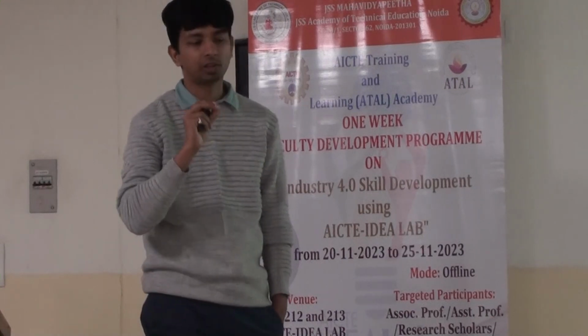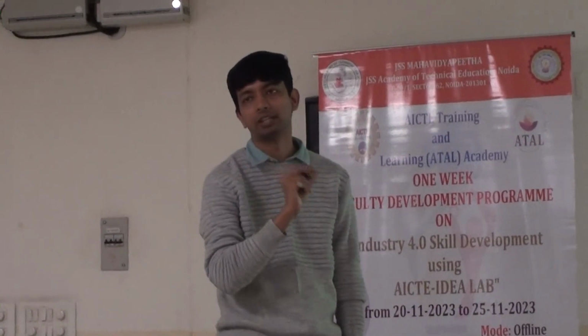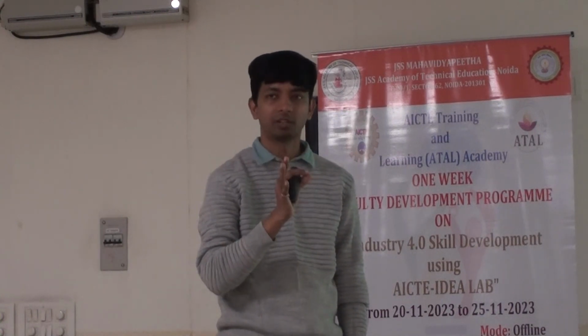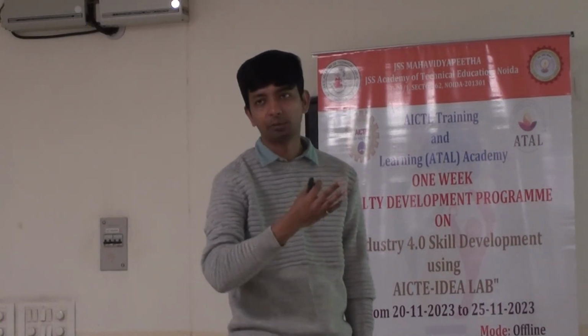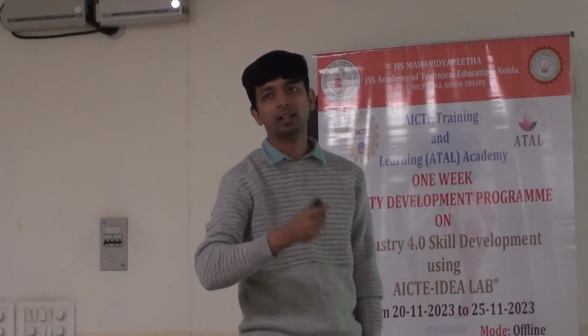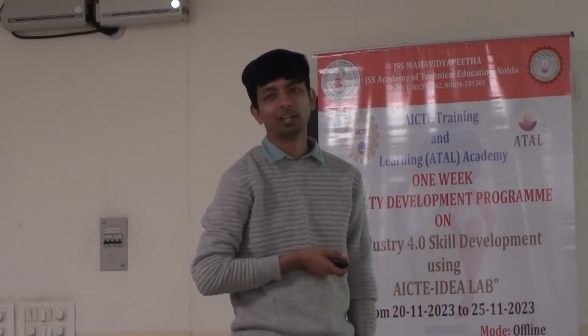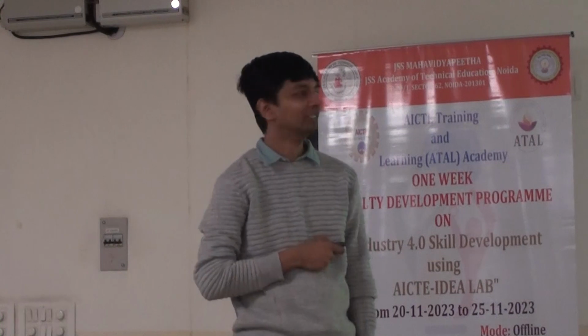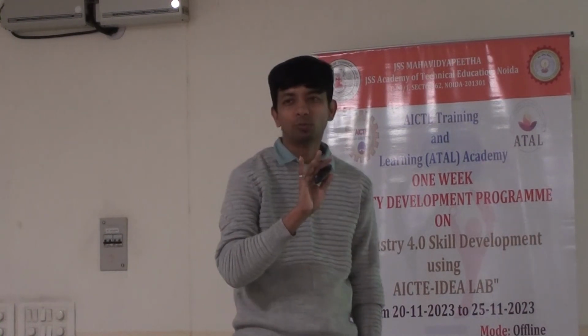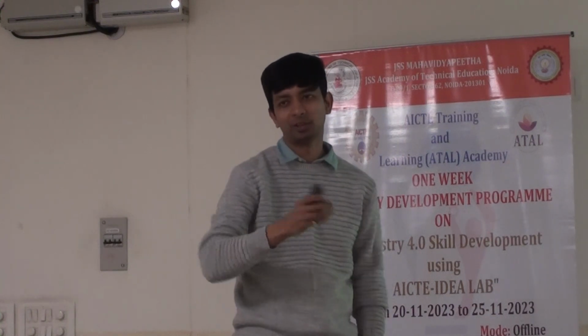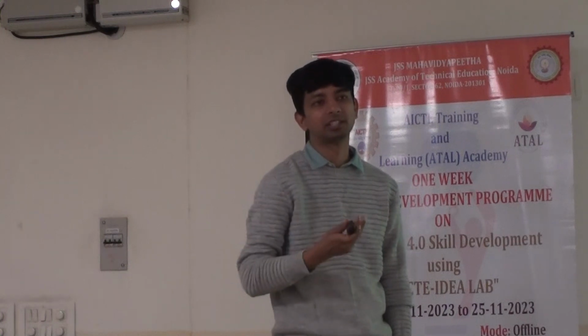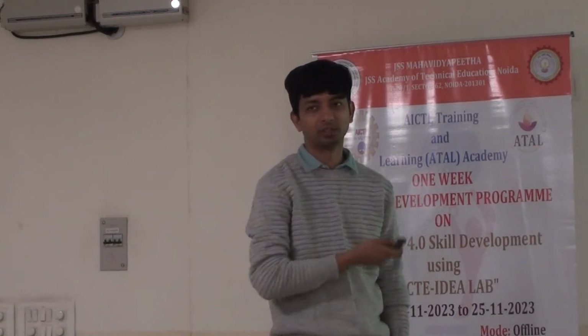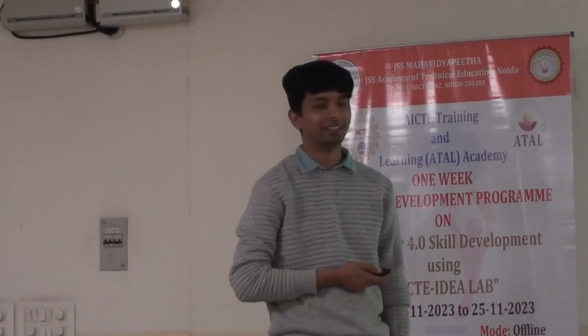Cold spray deposition, where you deposit the material at supersonic velocity without melting. So up to Mach 3, or 4. Because beyond that, if you increase the Mach speed too high, the flow becomes turbulent. That is not acceptable. Mach 3 is very high, sir. Normally 2 to 3 is the maximum, because beyond that it is not sustainable. It will form some kind of shock waves, and that creates problems. Okay, thank you, sir.